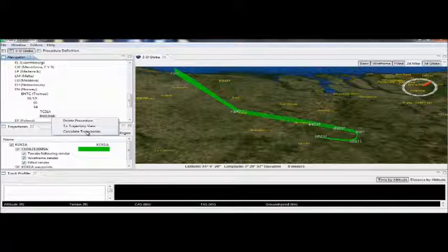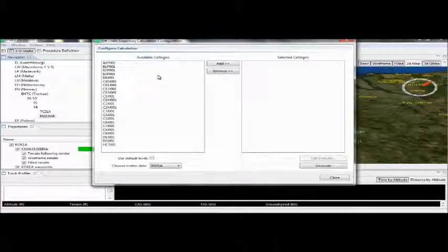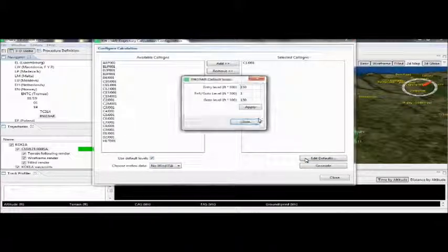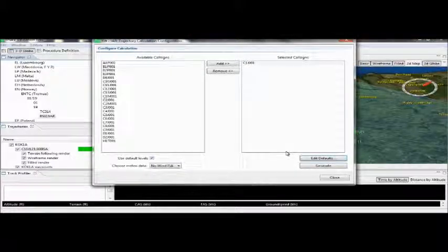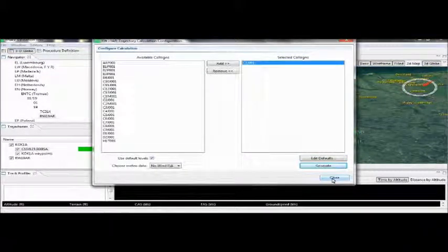we can also generate a trajectory. We have a number of aircraft types in a performance model, and you can select an aircraft type, determine the weather conditions under which you wish the aircraft to fly, set the default values for the procedure, in this case 150 descending to 10,000, the exit level is 100, and as you start the simulation it's descending to flight level 100. The procedure has been generated.